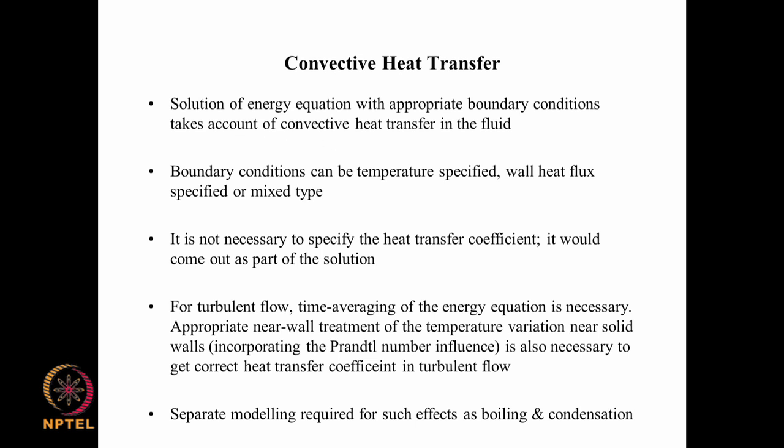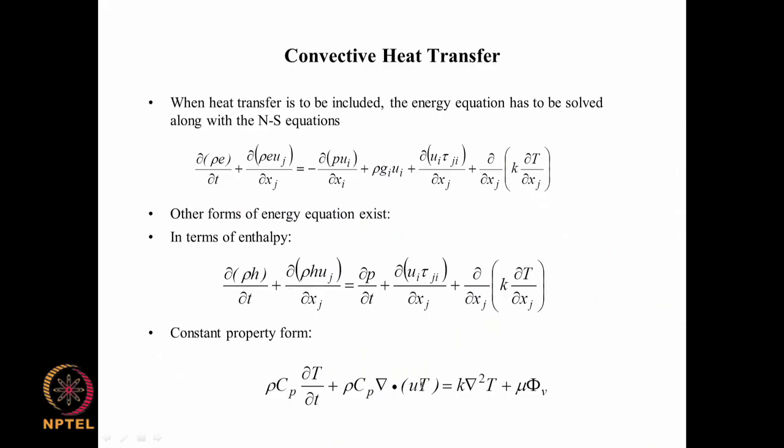Okay. So the important thing is that we don't have to do anything special to simulate convective heat transfer. It is already included in the governing equation for the energy because of this particular term here. The advection term is the only place where velocity is coming, and this will take care of the convective heat transfer.